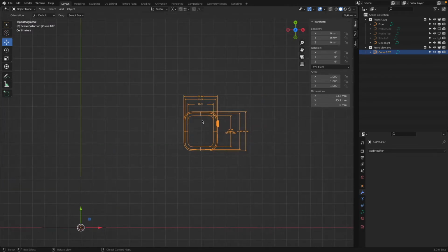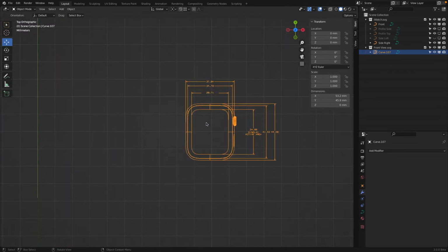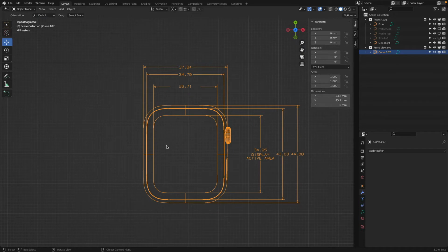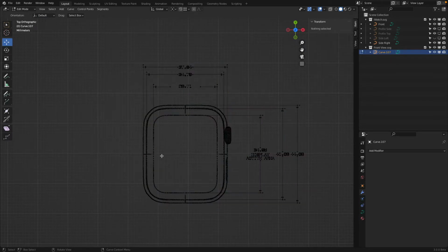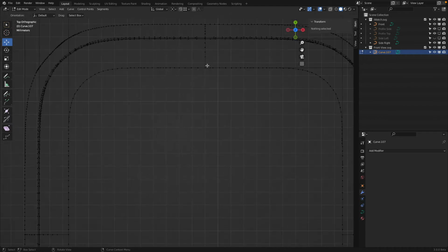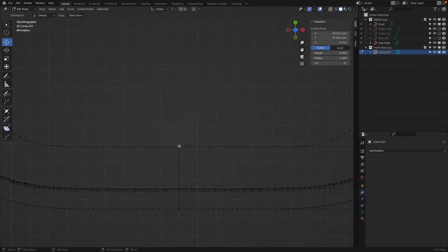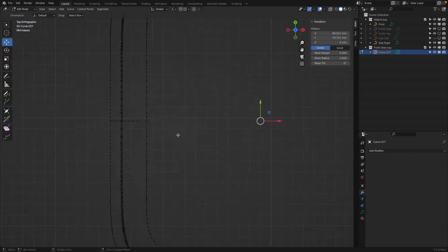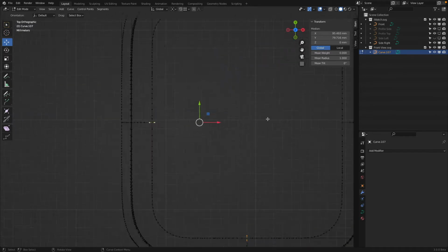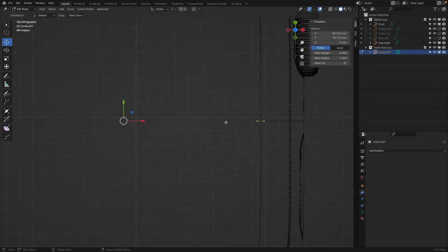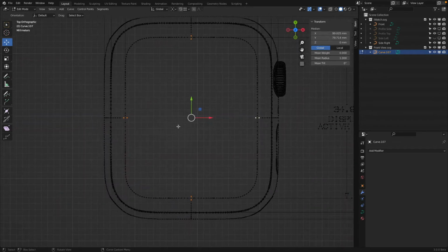There. Goodie. So now we need to center this where we have the rest, and we need to get this into scale. That's actually super easy also with an SVG object. First thing, we would like this to be centered. To do this, we can go into edit mode via Tab, and then I select these maybe four points there. If this document is done cleanly, this really should be at the center of these two lines.